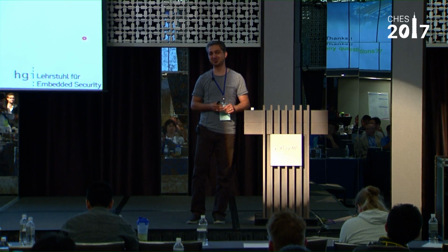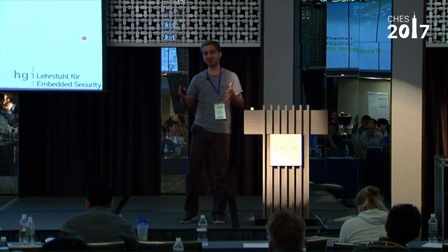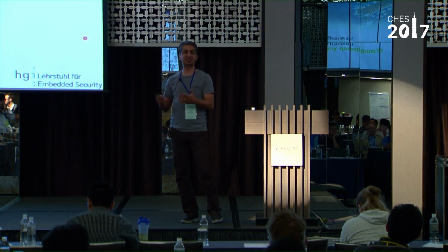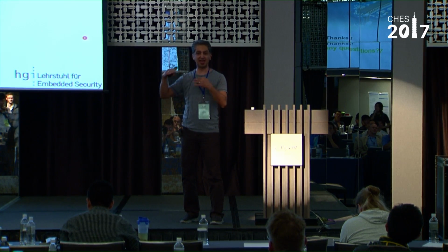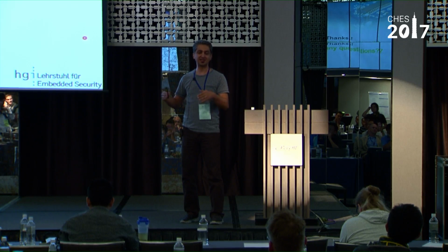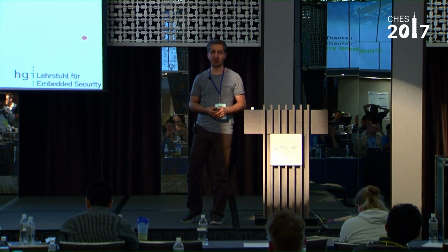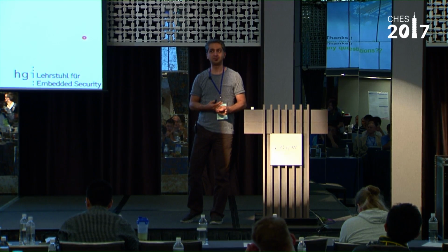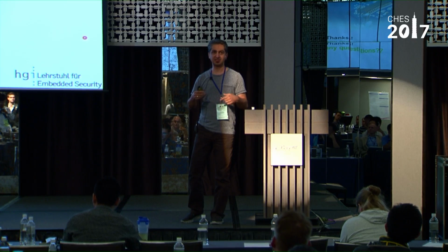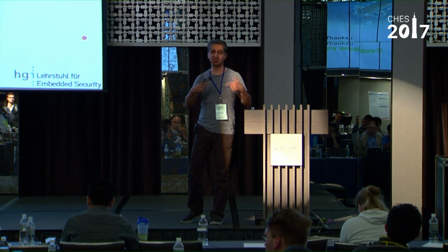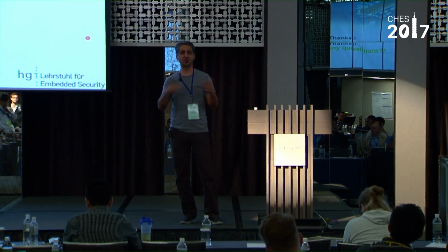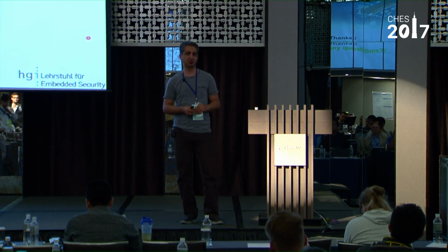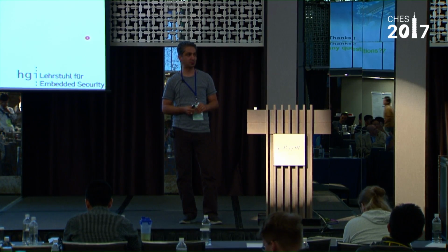Okay. Because usually it's like this: the synthesizer reports which cells of the library are used, and then there will be a list and the sum of the area of all these gates, divided by the area of the NAND gate. So the gates are not sized at all. They're all like 1x gates. No, the gates are selected based on the drive strength and so on. I think they should be okay unless we need to go to the back-end design, really. Okay, thank you.